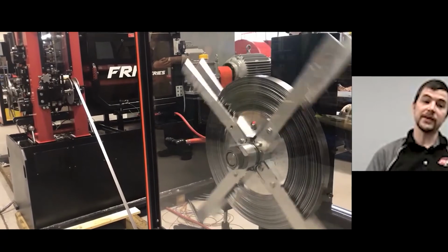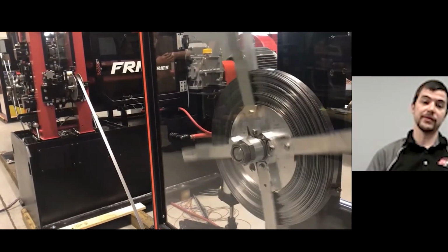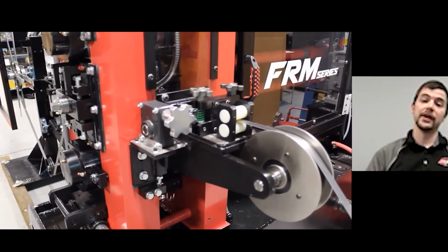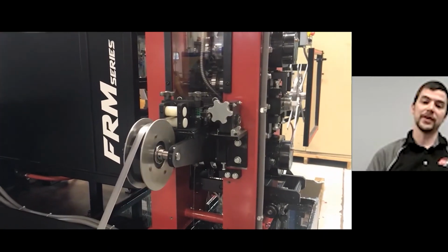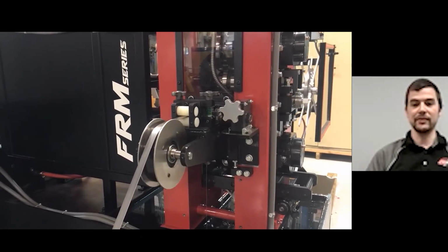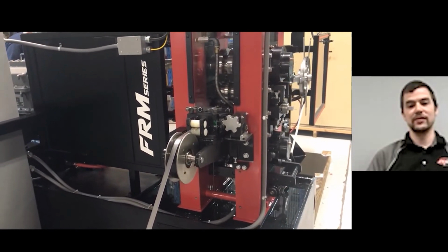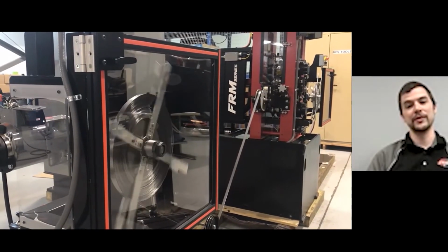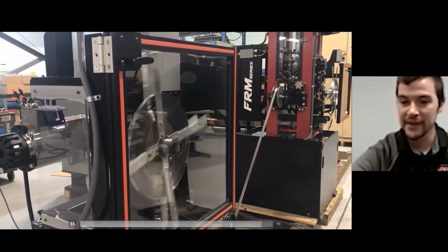This video gives you a rundown of an example of a single stand strip mill that we've done in the past. This one is running simple continuous coil feeding between a payoff and take-up winders. We're running simple guide pulleys with lean-on dancer arms to act as a speed and tension control loop, as well as continuous lubrication to keep the material well lubricated as it's feeding in between the two rollers. This is a simple standalone single stand continuous coil reversing mill, just to give you a visual of one of the other types of machines that we provide.